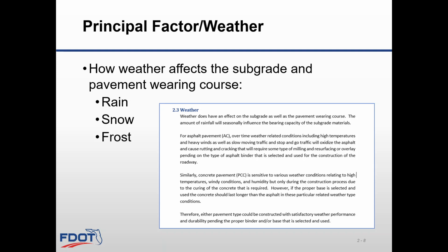Similar requirements exist for asphalt pavement, and these are covered under specs 330-3.1 and 330-3.2 that describe weather limitations for paving operations. And Table 330-1 covers the temperature requirements depending on the mixes. Here's an example of a pavement type selection report write-up for this principal factor.